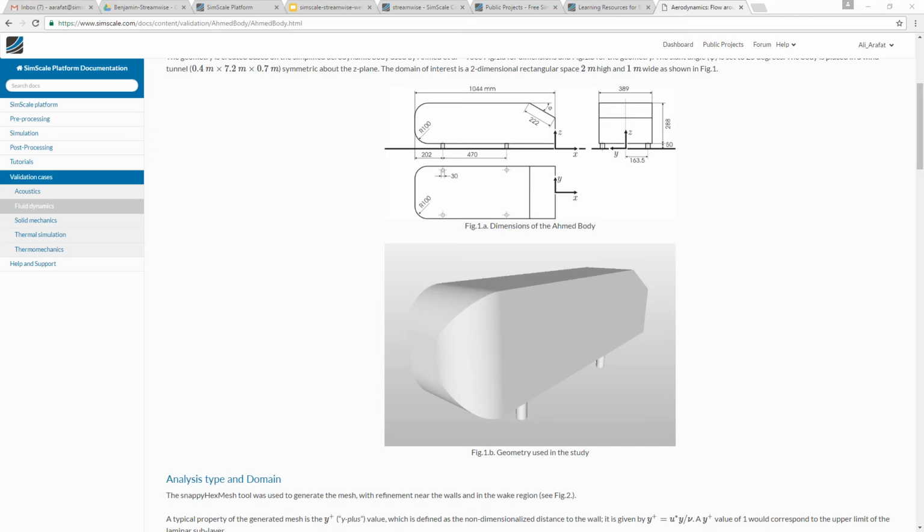This is not an issue of ProCap, it's an issue of available probes for such types of flows. You can combine any other probe which is more suitable with ProCap. But again, it's also a validation method which has, let's say, an engineering quality, so you have to focus on the areas where data really makes sense, and in the backflow region you have to know that you will not have the correct flow data acquired by the 5-hole probe. I hope that answers your question.